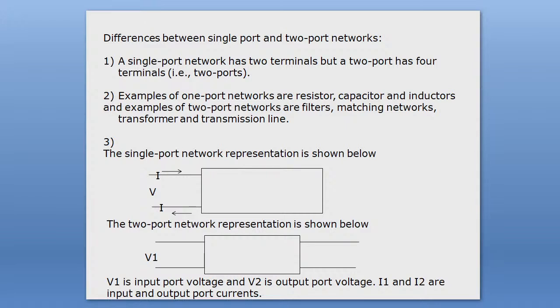We discussed the matching network when we covered the maximum power transfer theorem. You noticed that maximum power can be delivered from source to load when load resistance equals source resistance or the Thevenin resistance of the network. Such a situation is known as the matched condition.